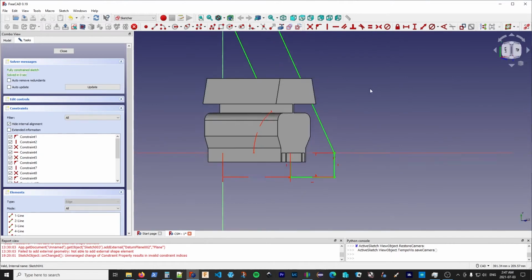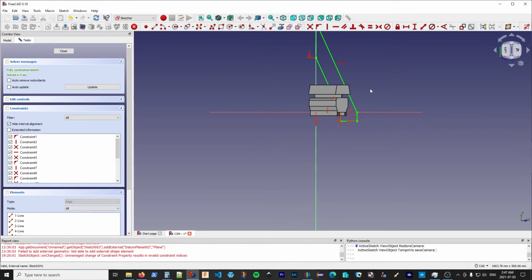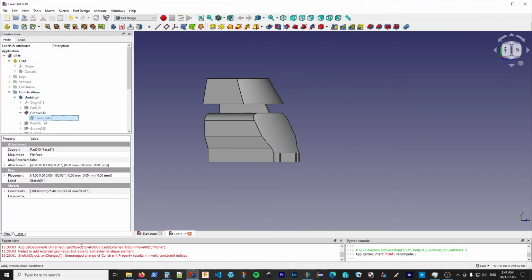Okay, so what we're doing is we're creating a groove section that we're going to rotate around the vertical. Okay, and it has to be a closed shape because that's what you're going to be doing the groove with. And you have as the inside shape the portion that you're going to cut. Okay. So as we do the groove, we've now got that basic shape.